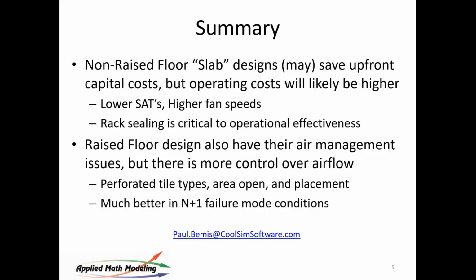Furthermore, in that non-raised design, the high-speed velocity air that's passing in front of those racks on the way down the aisle will cause a pressure differential that will make those servers work much harder because the air going by them is perpendicular to their intended direction. So that will cause the servers, what we call, to scream. The servers will scream because they're trying to cool and they're having difficulty operating due to their high differential pressure. So beware of this when you're designing these systems.